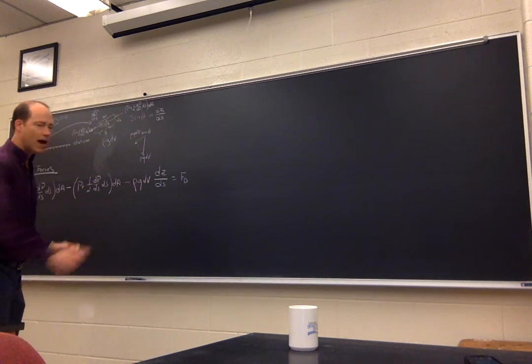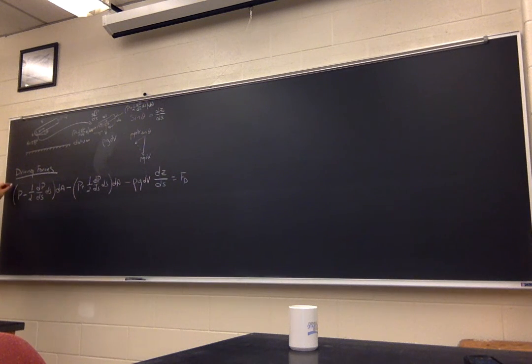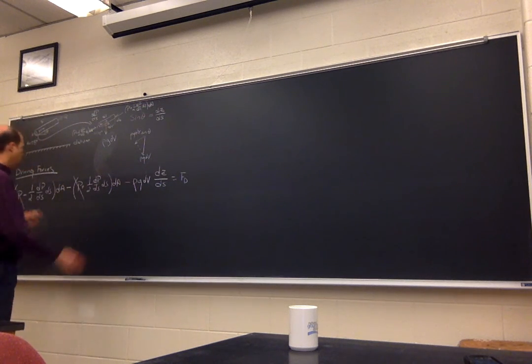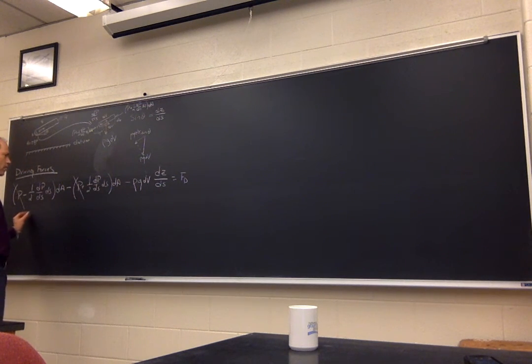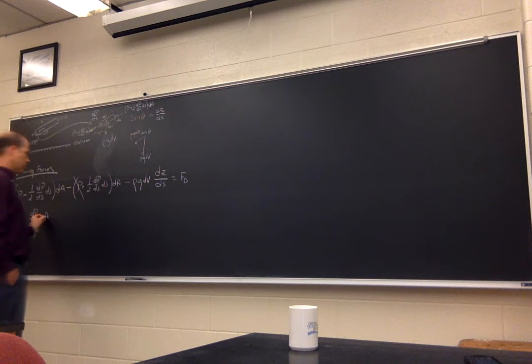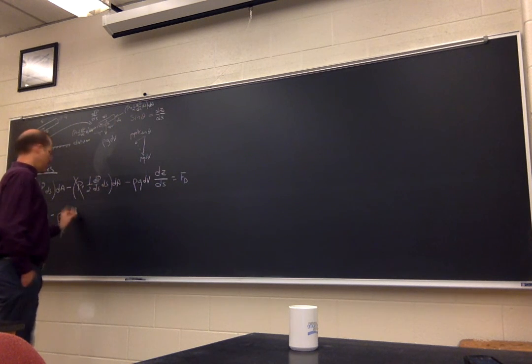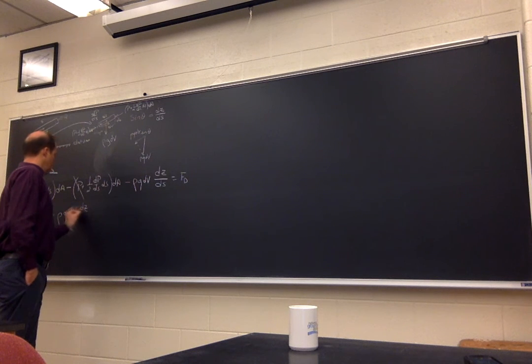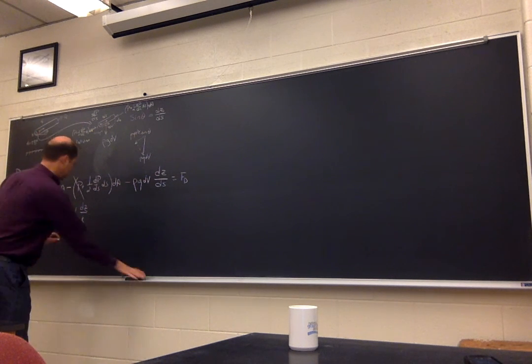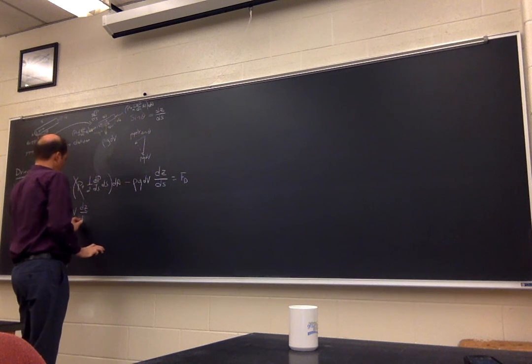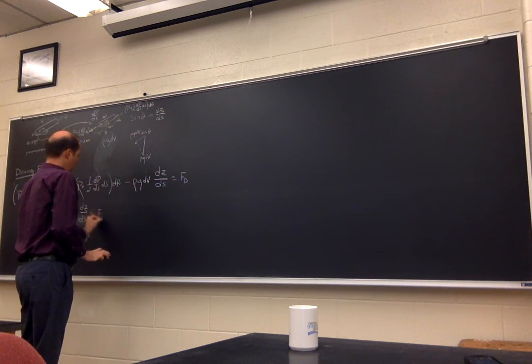Now we can simplify this part down pretty quickly because P minus P goes away, and minus a half minus another half becomes a whole, so that we have minus dP/ds ds dA minus rho g dV dz/ds equals the driving forces.